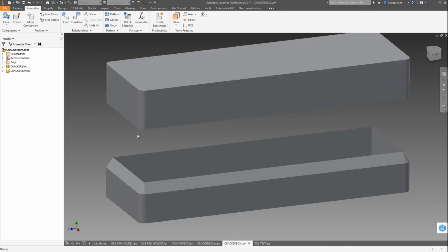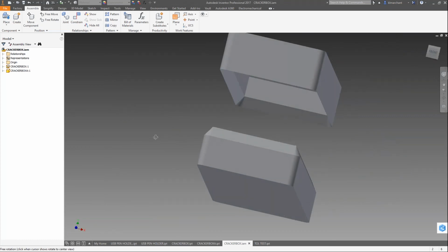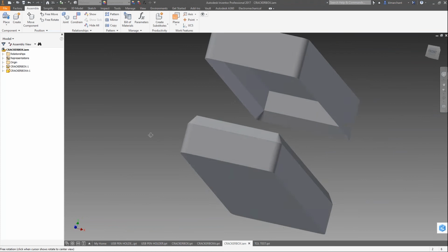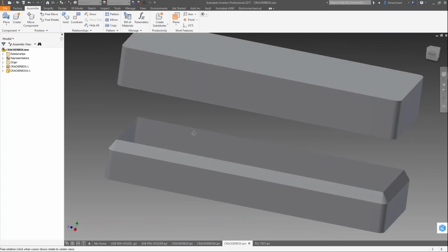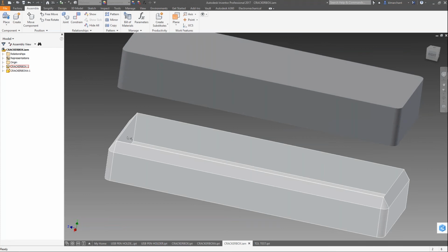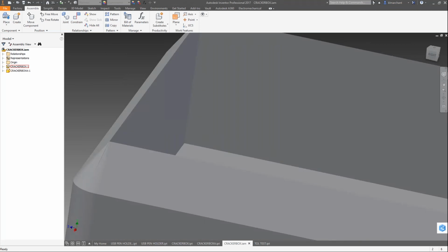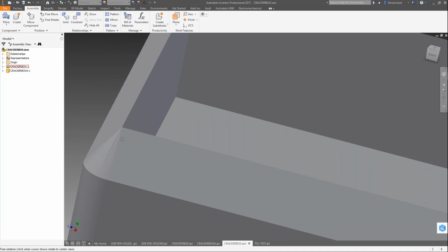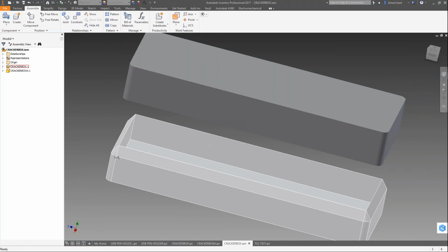And that's just due to the fact that when we print with an FDM or FFF technology, this is coming in here in layers. And so the layers across here, I want as much contact as I can to give as much strength as I can as well. And when we're talking about strength, if I look at just the wall thickness of this guy, if I pick the right two faces the first time, I've got an 1/8 of an inch wall.